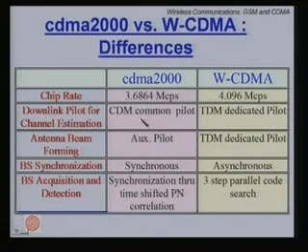So, in this table, we have the various parameters. For example, look at the chip rate. Chip rate is defined as the minimum chip interval used in the spreading codes. Chip rate is much smaller than the bit rate. The smaller the chip interval, the more the signal will be spread. Now, CDMA 2000, for example, uses 3.68 mega chips per second, whereas WCDMA uses 4.096 mega chips per second. There is no reason why they have to be different. Right? So, these are minor differences.